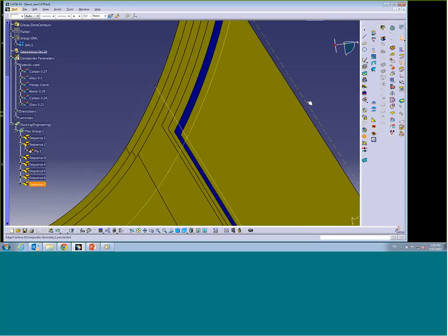So what I was getting to, you can work with manual plies creation. This works just fine. It's available with CATIA or FiberSim, any other package. The problem is working with ramps. So here I should have a drop-off. Instead of kind of steep drop-off, I would want to have like a gradual ramping down from thicker zone to a thinner zone, but it's not there.